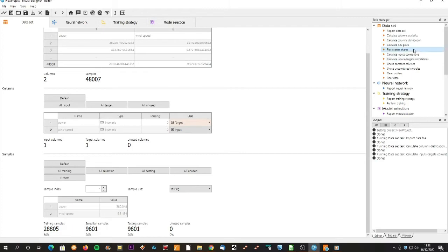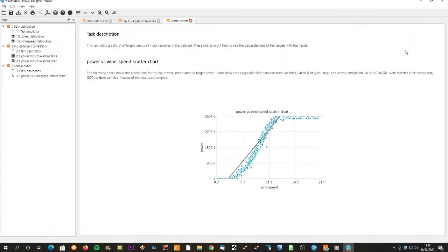To get some extra information, we can click the scatterplot functionality. There, we can see how there is almost a linear correlation between our variables, only broken for a starting threshold and a saturation threshold. The first one meaning that the turbines need a minimum amount of wind speed to work, and the latter meaning that there is a maximum power the turbines can generate.